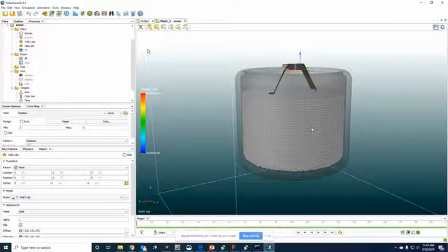In Particleworks in particular, the time step that you select is an important feature that can take some time getting used to. You also change the pressure model and the viscosity model in this simulation, and do all the CFD type work that you'd normally include in the simulation.